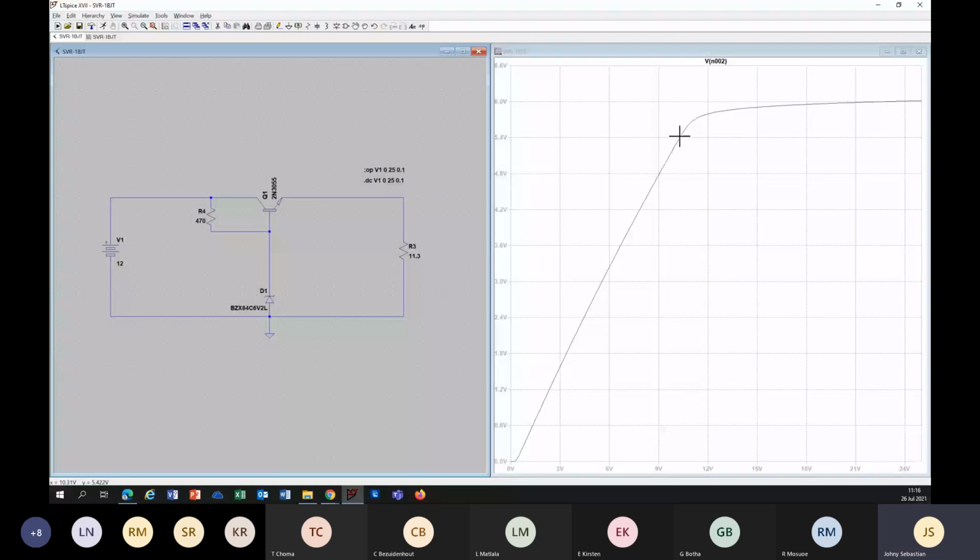When the input reaches 5.39, after that you can see that the output is flattening. By this voltage, when the input reaches around 21, output is at 6 volt. We were expecting somewhere around 5.5.